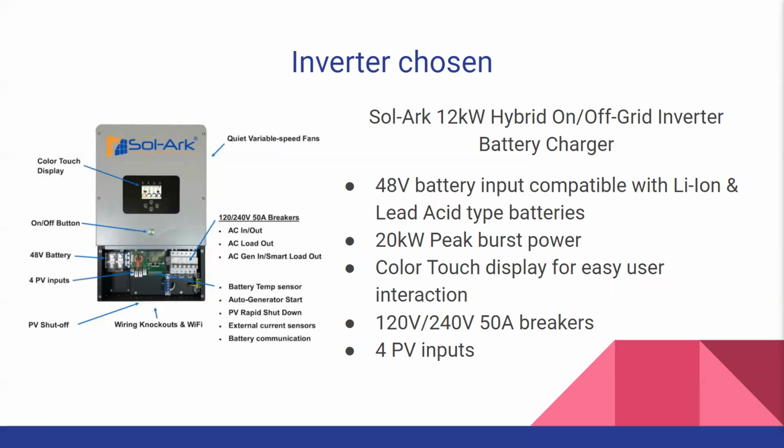The inverter chosen for this design was the SolArk 12 kilowatt hybrid on-off inverter. It can support up to a 48 volt battery input with either lithium-ion or lead-acid. It has a 20 kilowatt peak burst power, in addition to a color touch display for easy user interaction. It also has 4 PV inputs for multiple photovoltaic connections.